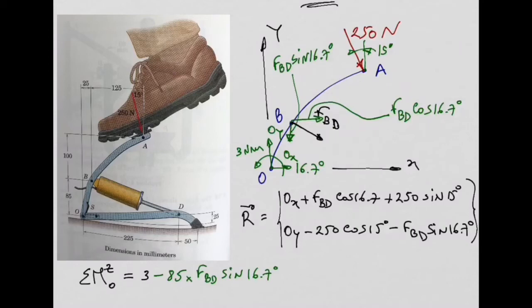Now, let's do the analysis for this component of the force. First, will the moment be clockwise or anti-clockwise? Clockwise. So minus again. This is the direction of my force, so I need to consider this distance, right?